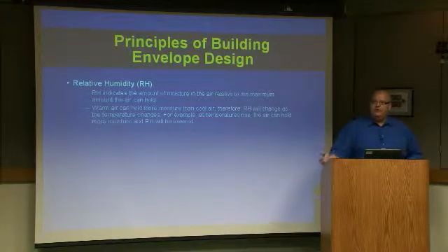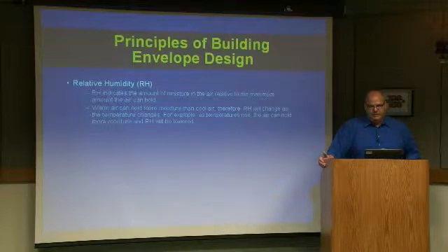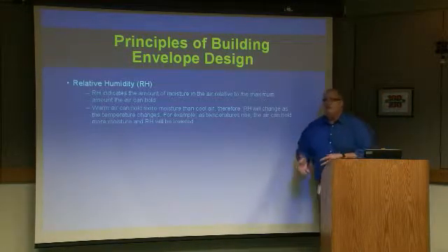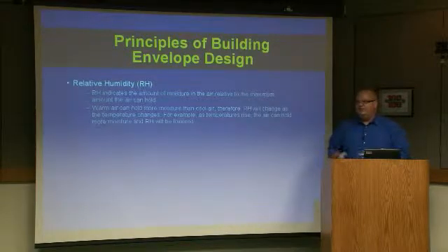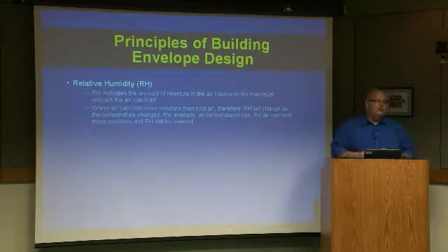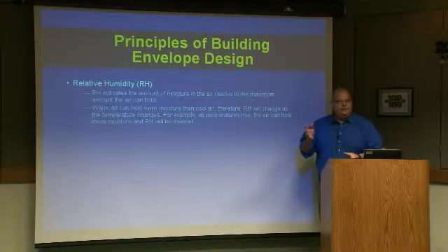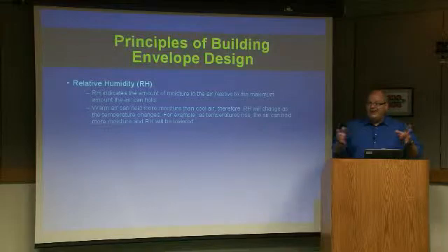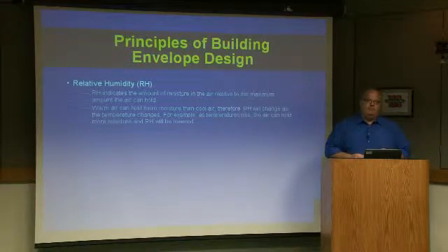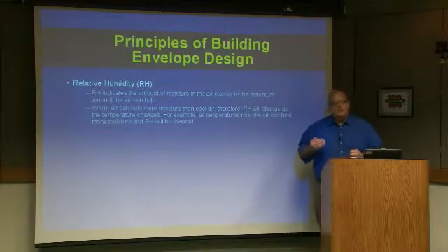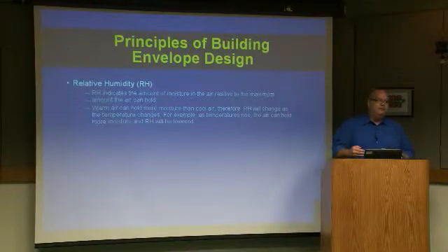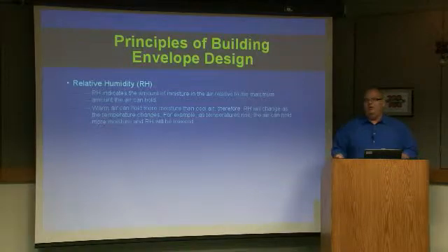When you have a material that goes above 17% wood moisture content, if there is food present, it will grow mold. So this is why we get to talking about designing for mold resistance. When we're designing for mold resistance, we're designing for low humidities. We have to keep the humidities interstitial to the envelope below 65% RH, ideally always below 80%. We never go above 80% relative humidity for 30 running days when temperatures are above 41 degrees Fahrenheit or below 104 at any layer of the envelope, or else we have mold growth potential.